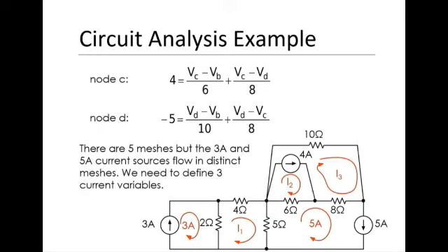Okay, so let's look at this node right here. It's much easier than the other. That node actually has 1, 2, 3, 4 connections. This node has 3 connections. So at least it'll make the analysis easier. So let's choose this one. There's a current going in, 4 amperes. The current flowing through this resistor is I2 minus 5. The current flowing through this resistor is I3 minus 5.